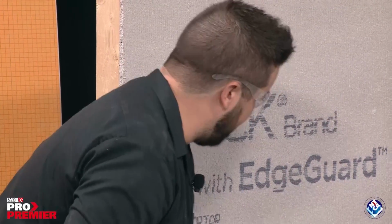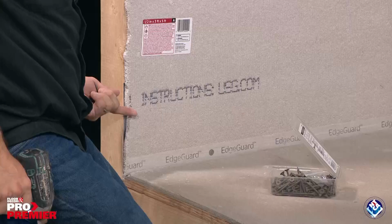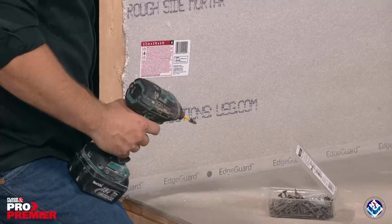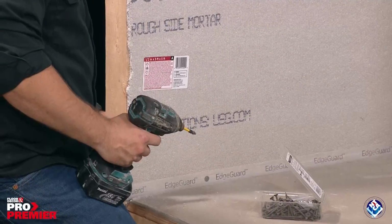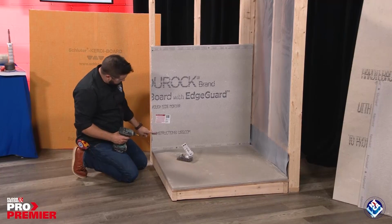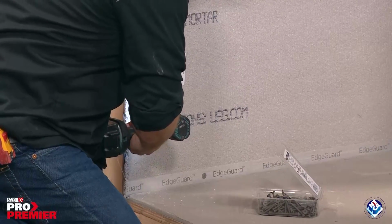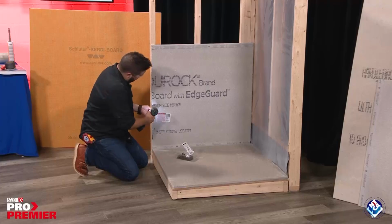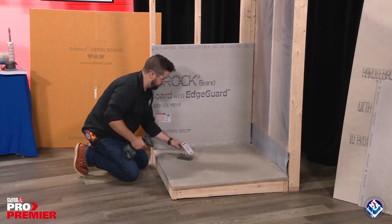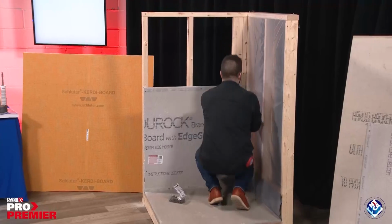And because this is a shower, we want to be cautious of how low we put our screws. We have our shower pan liner coming up here. Well, if we were to read into that detail, it says no fasteners lower than 3 inches above our curb. Well, we have an imaginary curb today, so I'm going to put a screw right here, and that's going to be our imaginary 3 inches. And again, I'm going about every 8 inches. I'm going to come over here and get this side as well.